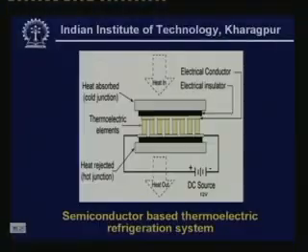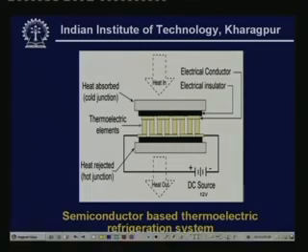However, they have the advantage that they are silent in operation, and they are very reliable, because you are not really using any mechanical component there. You can also use the same thermoelectric module for either heating or cooling, by changing the direction of current or electron flow. This is one of the advantages of thermoelectric systems. So let me show the working principle of a thermoelectric module.